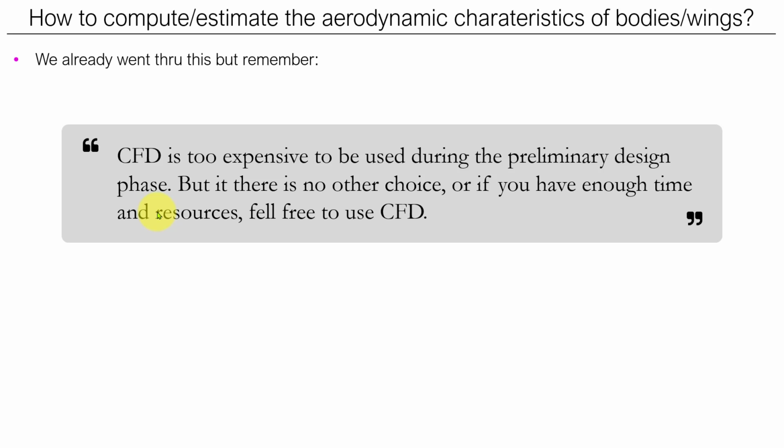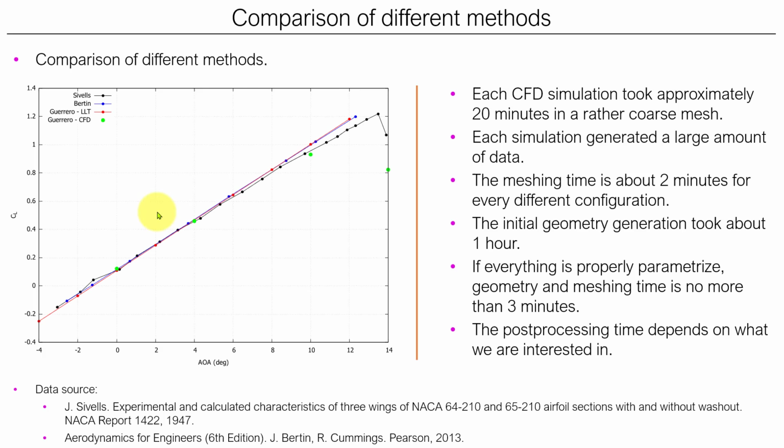But you will see that in the time it will take us to do one simple airfoil, probably you will do thousands of simulations using airfoils, also thousands of simulations using the LLT method or panel method or vortex lattice methods. You have done optimization, you have done a very good design. Instead, if you take CFD all the time that you just take to do one case, it will be equivalent to running thousands of simulations using the previous method.